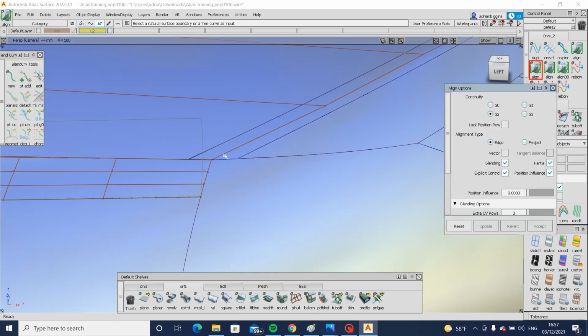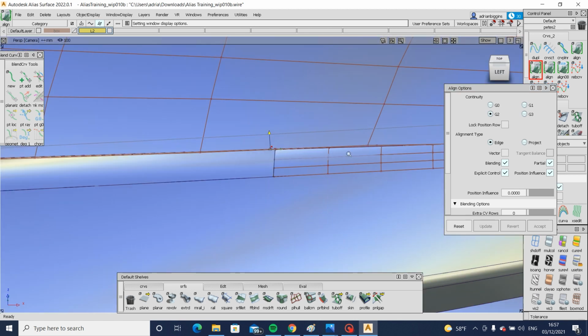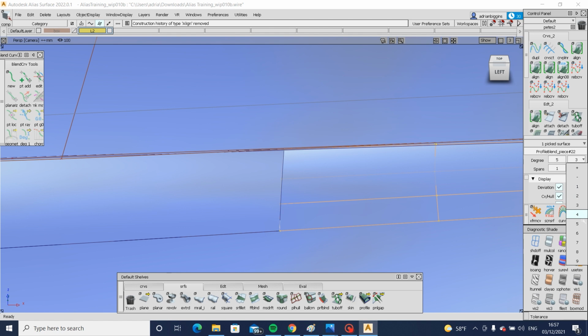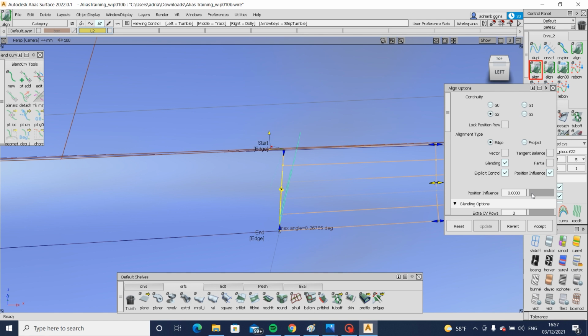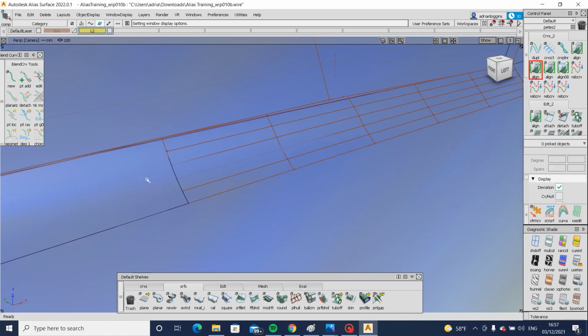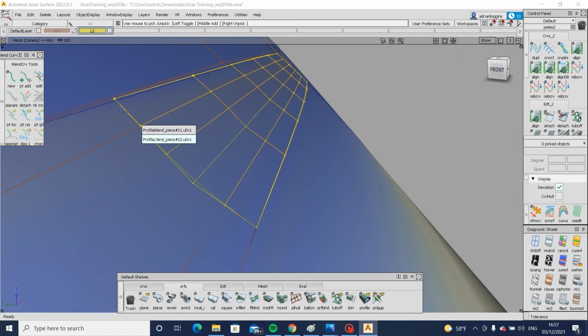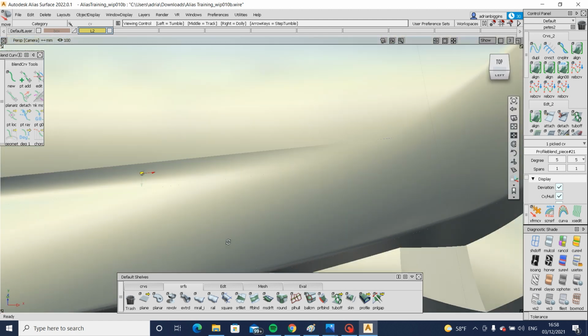I'm going to realign this edge. It's going to be still slightly different to the image, but if anything I think I've improved it. So there you go, nice. And delete the history on that, bring it back up to 5, and realign its curvature to the previous fillet. And that looks alright. It's still not perfect, but we can tweak that thanks to this. We can drive it with this CV, just pump it down. Same with this one. Pump it in. Oh, too far out. Same with this one again. Put that down and in. How's that look? Quite nice. Good.